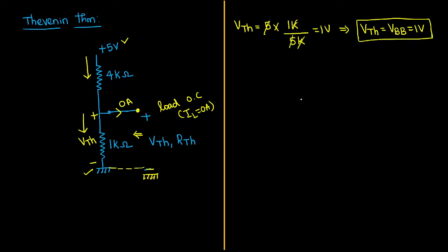Last question, previously we already saw the same model type. Now how will you calculate the RTH? To calculate the value of RTH, we have to do one more thing extra. Basically, while dealing with the VTH, we are not deactivating the independent source. But while calculating the value of RTH, all independent sources will be deactivated.